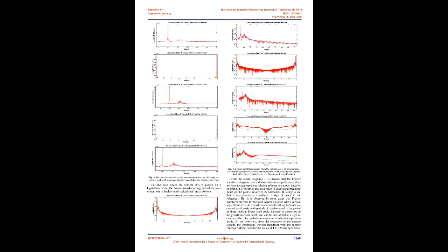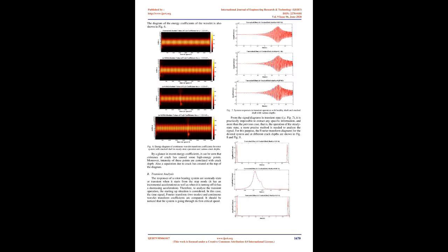D. Obtaining the system response and analyzing the answers. For the rotor-bearing system with a midspan disk having the following properties: L equals 510×10^-3 m, MD equals 5.5 kg, D equals 20×10^-3 m, ρ equals 7800 kg/m³, E equals 2.08×10^11 N/m², e equals 0.01×10^-3 m, CB equals 100 N·s/m, KB equals 10^5 N/m, ID equals 0.01546. We obtain the number of elements n equals 15, and the system's response in the transverse direction.